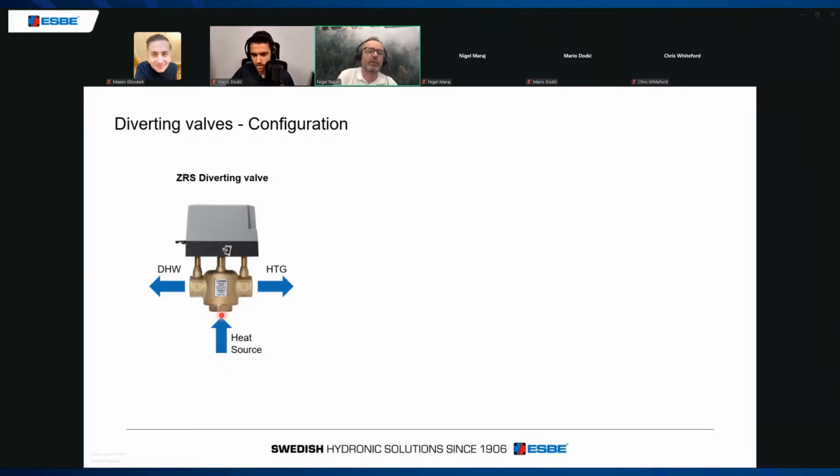I call this the branch, but always in from the middle. And then within here, and I'll show you a video of this, or actually we've got it live on the camera slightly later, there's a rubber ball, and this almost swings like a pendulum by the motor, from blocking off one port when you want the heating circuit and blocks off the other when you want the hot water circuit.